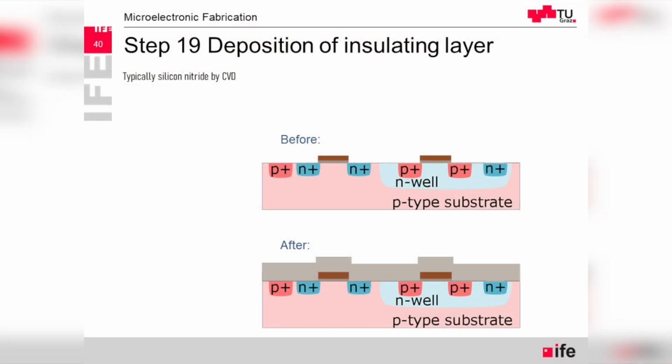So I will not rewind the slides again through here. That was basically what we have done so far. We have done the self-aligned implanting of the N+ and P+ regions for source and drain, as well as not self-aligned, but under certain control as well, contacts for the bulk, for the P-channel transistor and N-channel transistor. So from now on, we're going to lower temperature processes because now what we are interested in is depositing of the metals. So again, there is a deposition of the layer for masking.